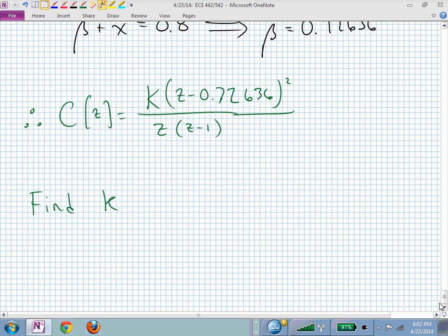We now know the root locus in general is going through those triangles because of the phase angle condition, but now we need to fix those right at the triangle. We're going to find k to place the closed loop poles at z delta equal to 0.8 plus j 0.2.